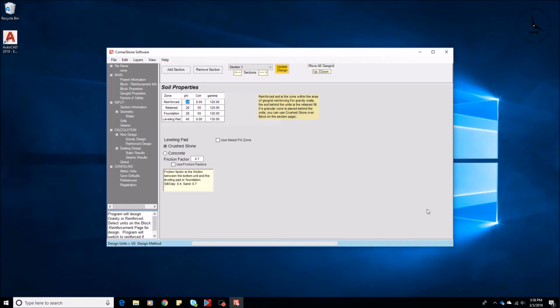A silty sand is going to be from that silt range, 28 to 30, depending on the amount of silt in it. When we go to more of a clean sand and gravel, we're going to be in that 30 to 32 range, and we have select backfill, meaning low fines content, less than 20% fines, sand and gravel mix.